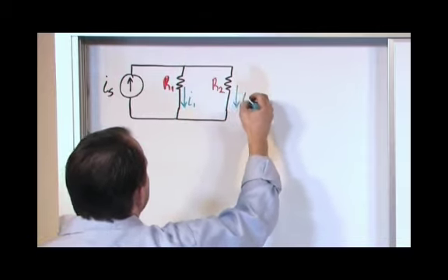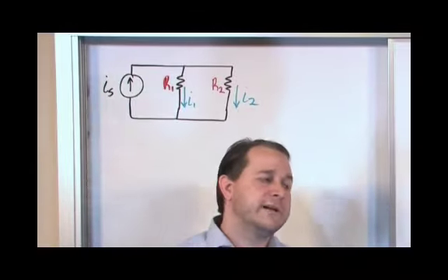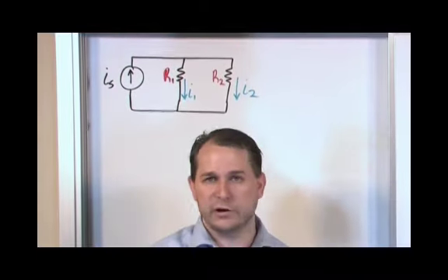You know from experience that the current is going to flow up, hit this node, and part of it is going to go here, part of it is going to go here. This is the current division. The junction points, the nodes, are where the current splits. So when you do a current divider circuit, you're trying to take your source current, whatever it is, and split it up so that you can get 2 amps or whatever you need to go into your particular load.